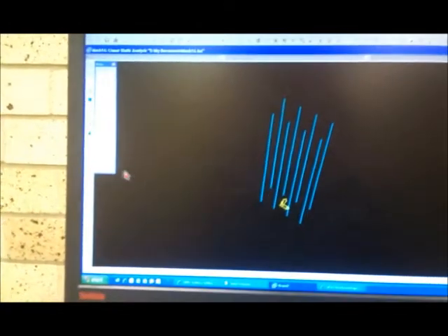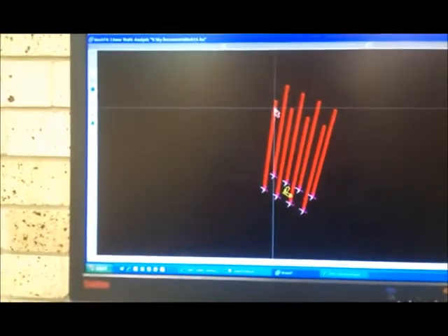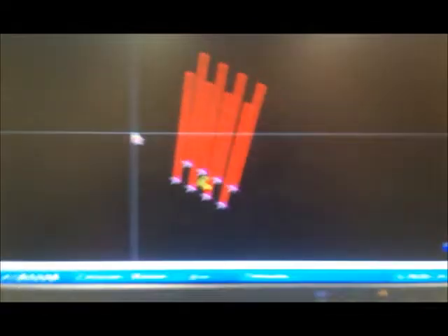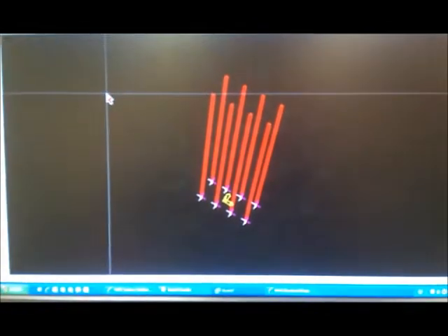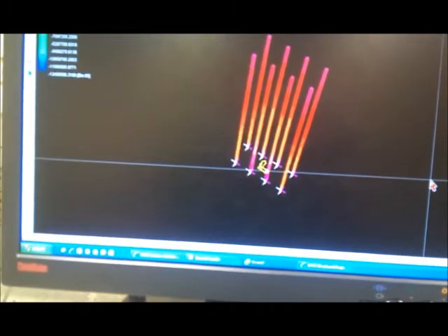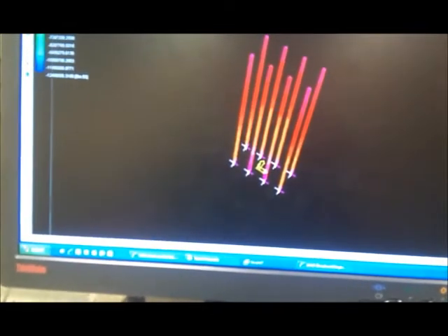These are the columns. We'll pass. I will check the stress in these columns due to this combination. So I'll go right mouse click, result settings, beams, which is also the same for columns, contour, stress. What type of stress do we want? Axial. We want axial, and then I'll say okay. So that's axial stress in the columns. And as you can see, they are all under compression.